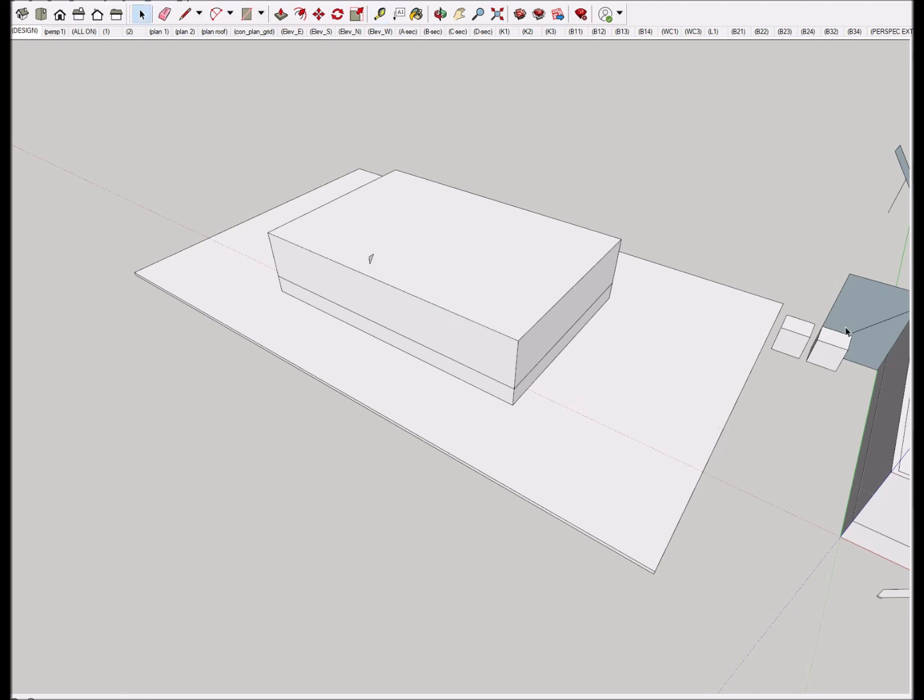Okay, so now we have our first floor, and then we're going to add a second floor on top of that. There's going to be some floor framing. I've assumed nominal 12-inch deep joists with a plywood floor deck and based the thickness on that, again using standard materials. Now the next step here, I'm going to put walls on top of that second floor. And again, I've made it 8 foot 1 1/8 high.